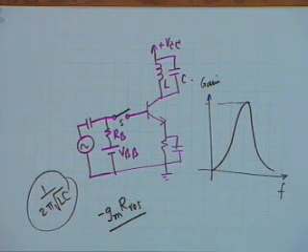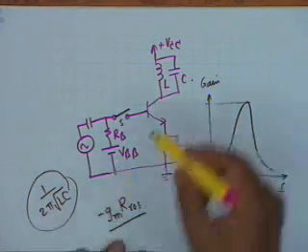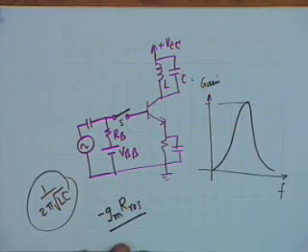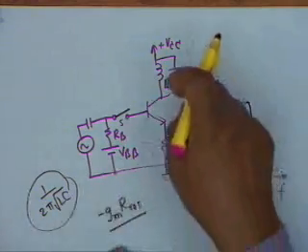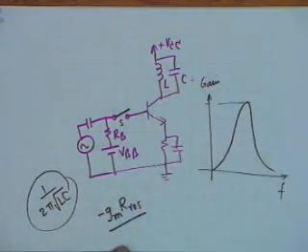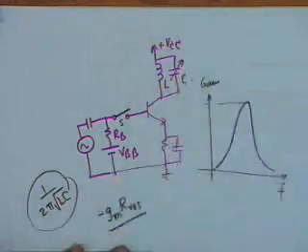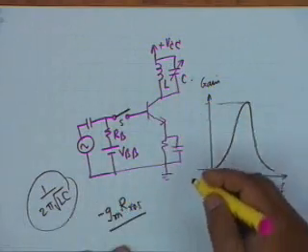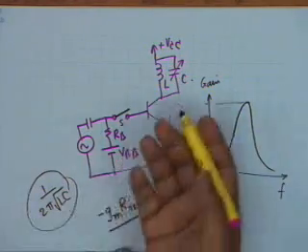Now, is this point clear? Instead of a resistance, I have an LC circuit here, and if I have an LC circuit, then the gain shall be maximum at the frequency of resonance, and you know that if we vary the capacitance, then the resonance frequency can be changed. This is what we do in the input stage of an ordinary radio receiver. We actually vary a capacitor so as to vary the frequency at which the gain is a maximum, and it is this frequency which shall be picked up by your radio.